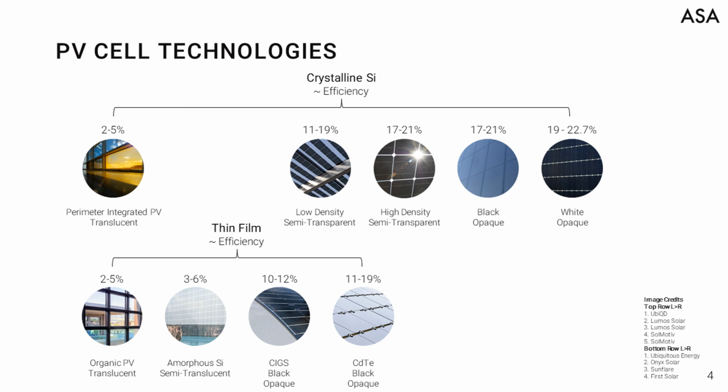When it comes to thin film solar cells, they are typically produced directly on the glass that encapsulates them. The result is a significantly thinner solar cell that is typically about 30 times thinner than a silicon cell. Historically, thin film efficiencies have lagged behind crystalline, but cadmium telluride modules have approached a 20% efficiency and are becoming more cost-effective to produce domestically.